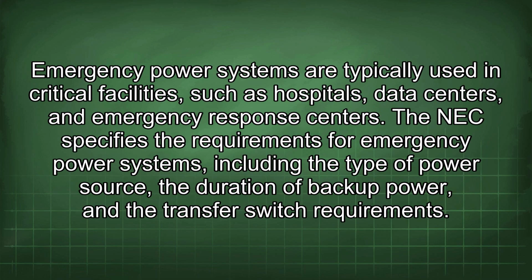Emergency power systems are typically used in critical facilities such as hospitals, data centers, and emergency response centers. The NEC specifies the requirements for emergency power systems, including the type of power source, the duration of backup power, and the transfer switch requirements.